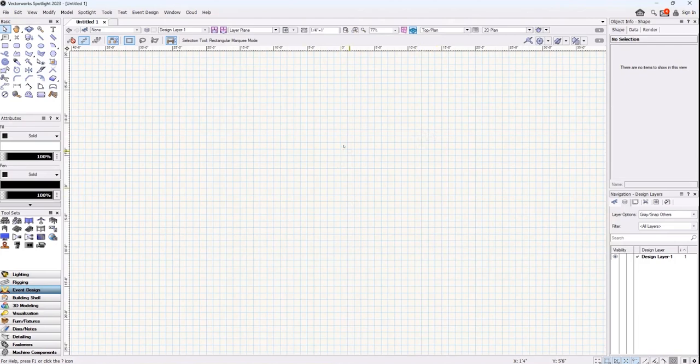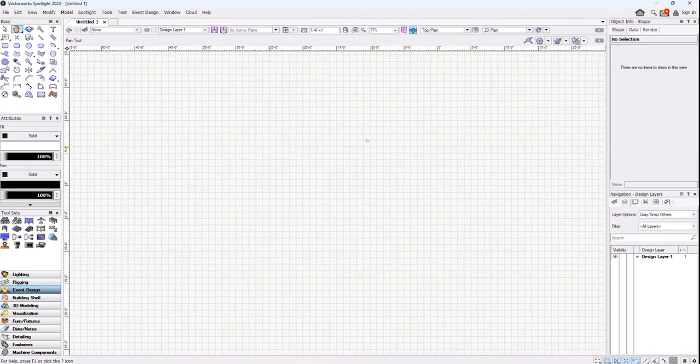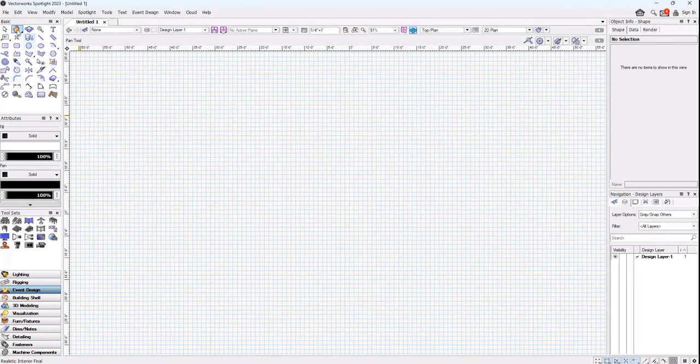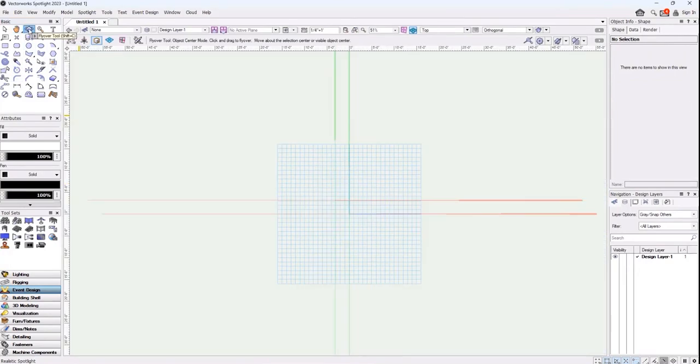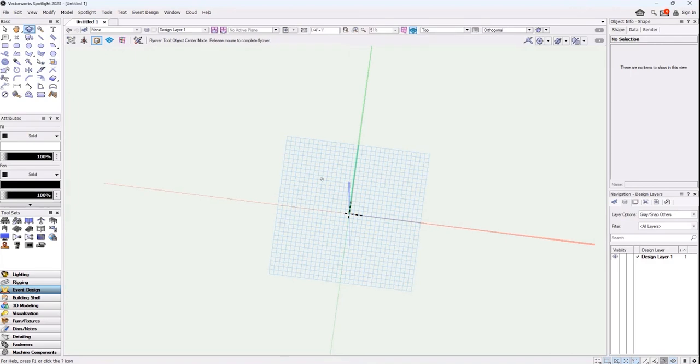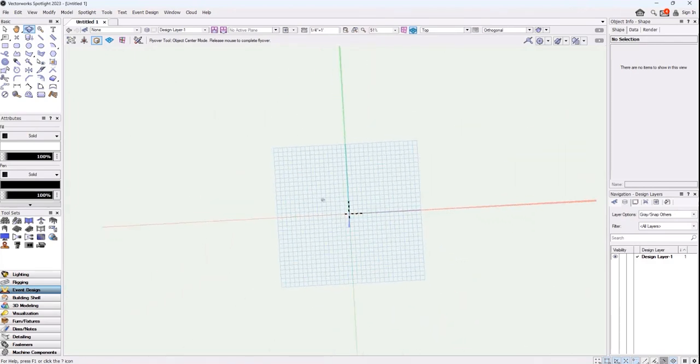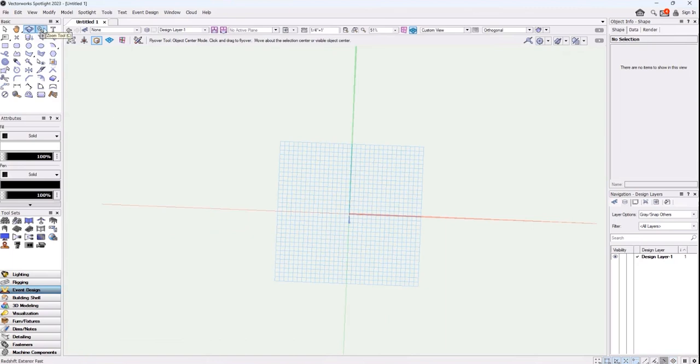Right now, we're just going to start with a very basic square, so we go over here to our tools section. This pointer is a selection tool. The hand actually allows you to move the workspace around, which pushing down on the roller button will also give you that option. Flyover tool, or as I like to call it Saturn, allows us to spin the workspace in 3 dimensions, which we'll see after we make our first little cube here. And then a zoom tool, text tools, callouts, and other things. But right now, what we'll do is start by making a basic square.